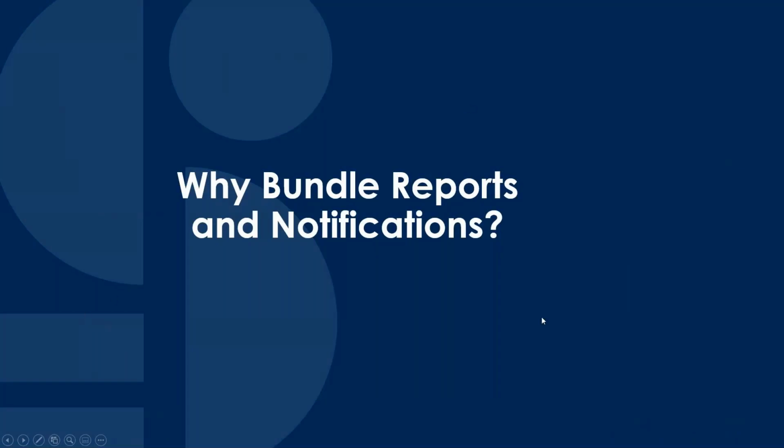So why would we bundle these two capabilities together, notifications and reports? We can certainly think that in water specifically, we can see how remote notifications are beneficial. It allows people to work remotely, to work off-site, or it allows alarms to reach them off hours at night when they're not in the plant. We can now run unmanned overnight shifts. It enables much more flexibility and better response time to our alarms.